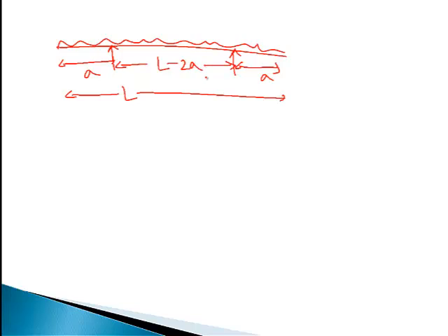Now, first of all, the bending moment and the reaction. So, reaction you can find out with the convenient method of finding the reaction, taking moment about this point or this point, or if you see the loading is symmetrical, if it is W, just divide the total load in the reaction.